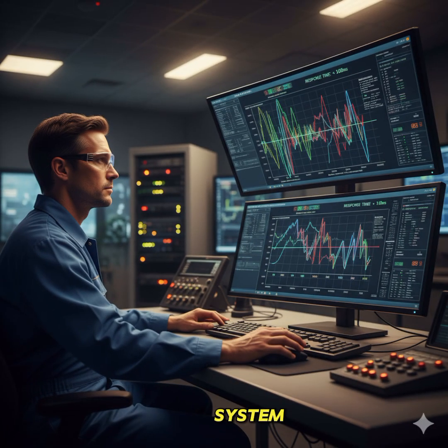If you're designing a system, here's how to choose. Choose SCADA if you need to monitor geographically dispersed assets. Data logging, alarms, and remote control are the priorities. Real-time response isn't mission critical.